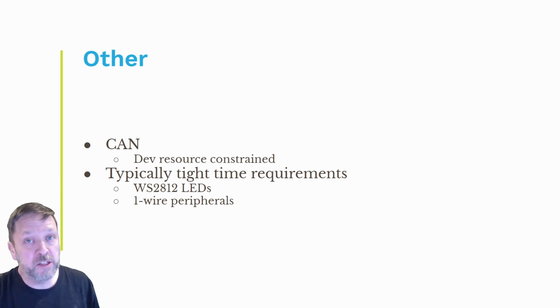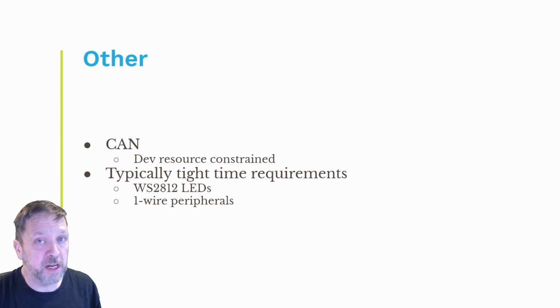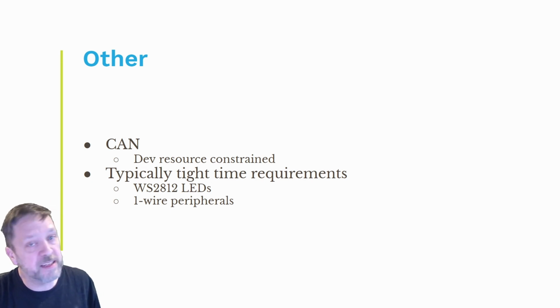Now, that very small bit time is really difficult to achieve in managed code, especially with garbage collection where you may have pauses in it. So it's difficult to reliably have bit times that will drive these peripherals. We are looking to either push the driver down into the real-time operating system or potentially a separate controller. So that's how those work.